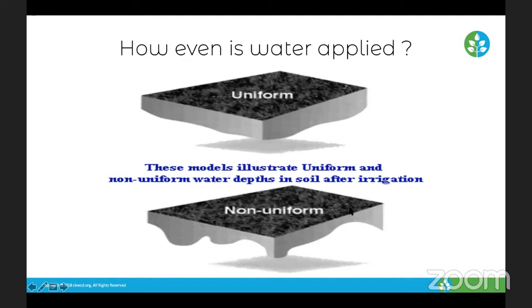We would see these inefficiencies, and the typical thing we would do is, oh, we need to put more water. So I've seen a lot of areas over the summer, especially over the last month, where we were having 100 degree days day in and day out. We started seeing a lot more brown spots pop up in people's lawns. And it's not necessarily because they're not running their irrigation system long enough, it's probably they have low distribution uniformity. Those are the areas that don't get quite enough. Well, some areas are getting way more than they need.